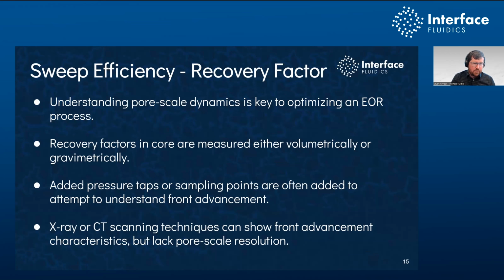So getting into that quantification, what are the things that we're measuring at Interface? First is sweeping efficiency or recovery factor. So these data sets allow us to understand pore scale dynamics, which allows our engineering clients to optimize their EOR process. Recovery factors in core are measured typically volumetrically or gravimetrically, whereas at Interface, we measure our sweeping efficiency visually. So we look at where was the oil and where is the oil not now.